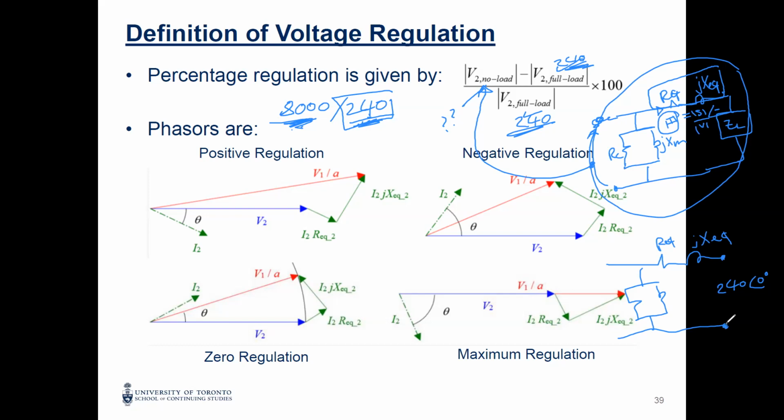If they are giving the R equivalent and the X equivalent, we will put it. If they have the P short circuit and the I short circuit and the V short circuit, I can calculate it. But can you calculate this current? Yes. This current they will give you in the exam, like full load or half load, for example.